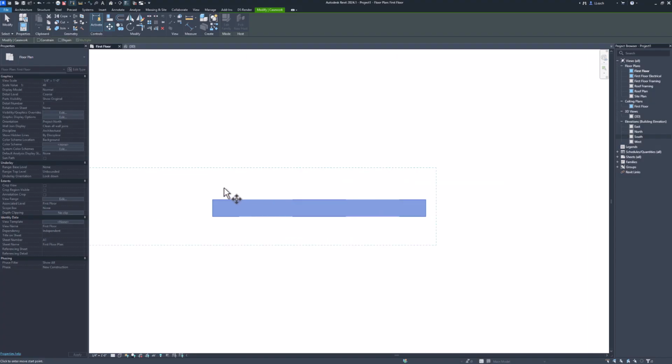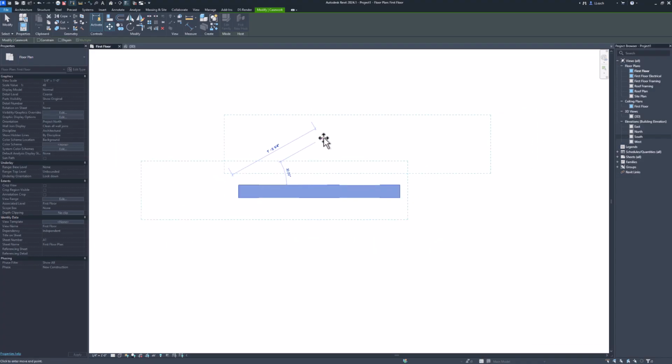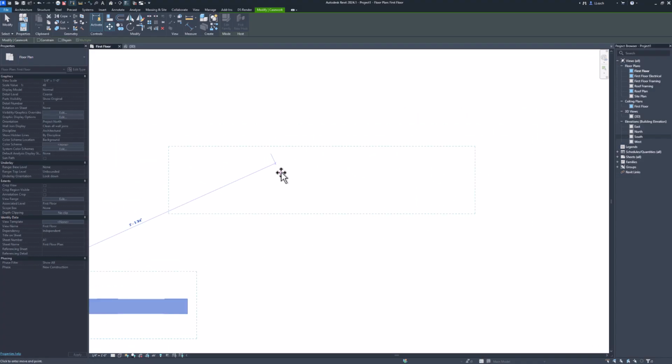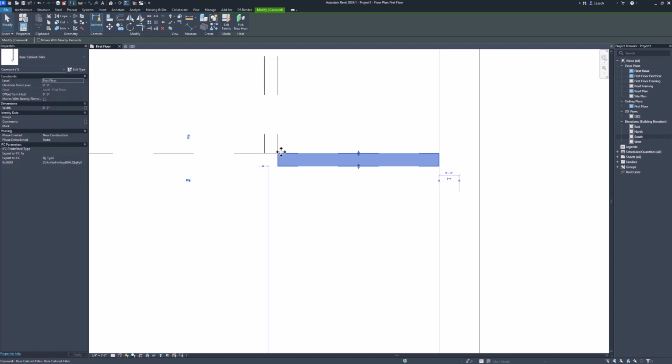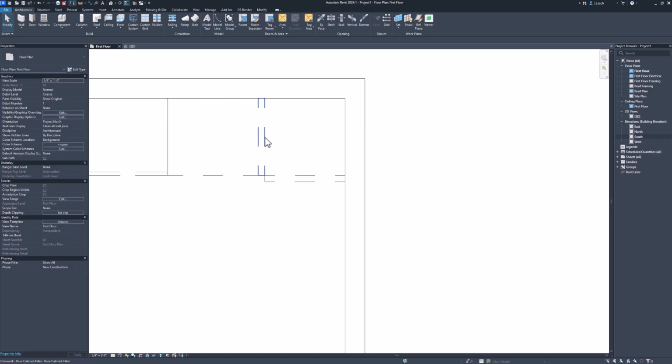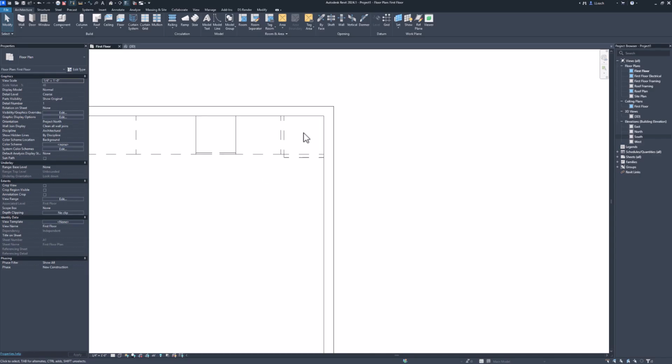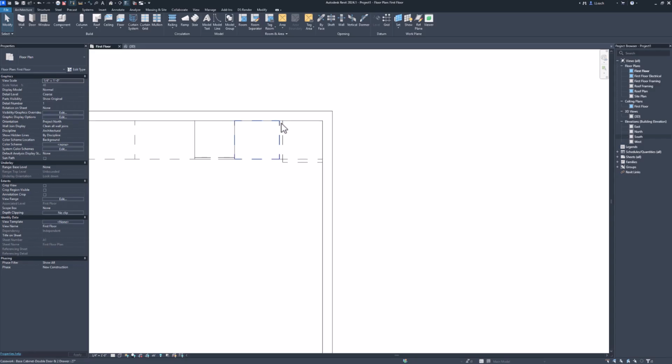And I'm going to move it from this left corner here to this corner here. So they're kind of like going like that. So you have a 2-inch filler here, 2-inch filler there. There's an empty gap in there. Our countertop's going to go over the top of that and cover up that little cubby hole.